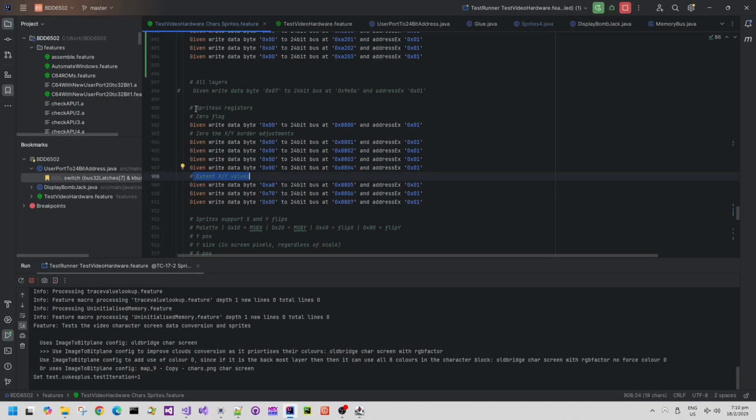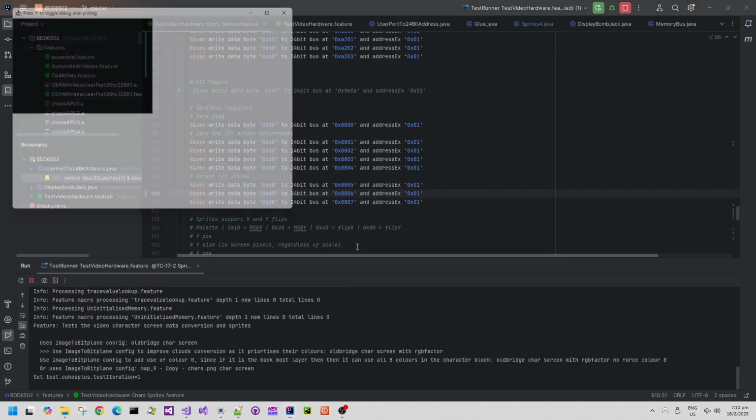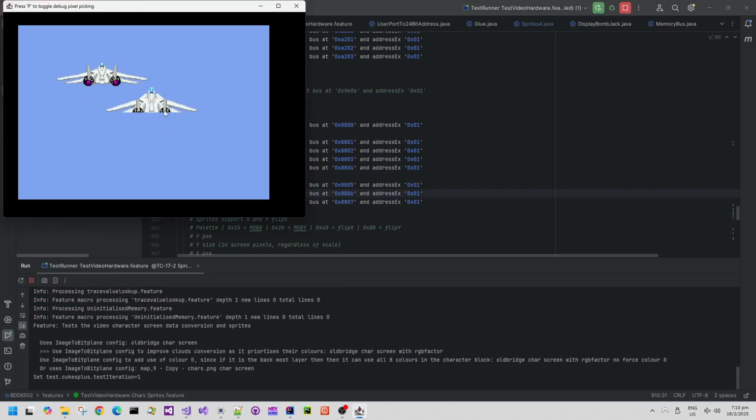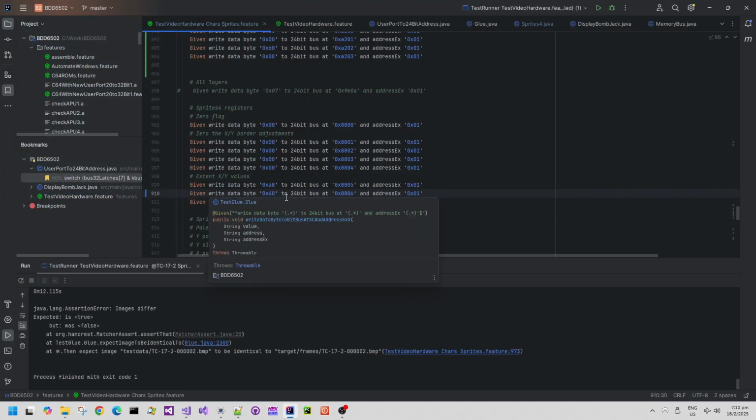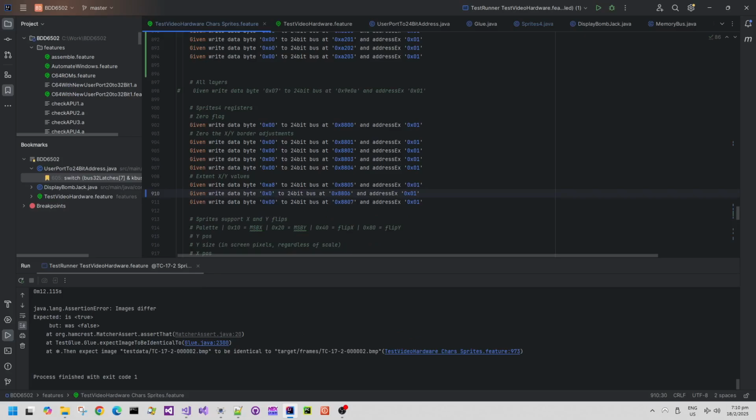Ah, there we go. Okay, so the sprites hardware, the super scaled sprites hardware, has the notion of clipping windows. So it has an origin and it also has extent values, which means that I can actually have a clipping window that the scaled sprites can render into approximately. It's a good way of saving draw time. If the sprite hardware realizes that it's going to be rendering pixels outside of this clipping window, then it will just move on to the next sprite when it can, and it saves all of that time. So that's what I've done there.